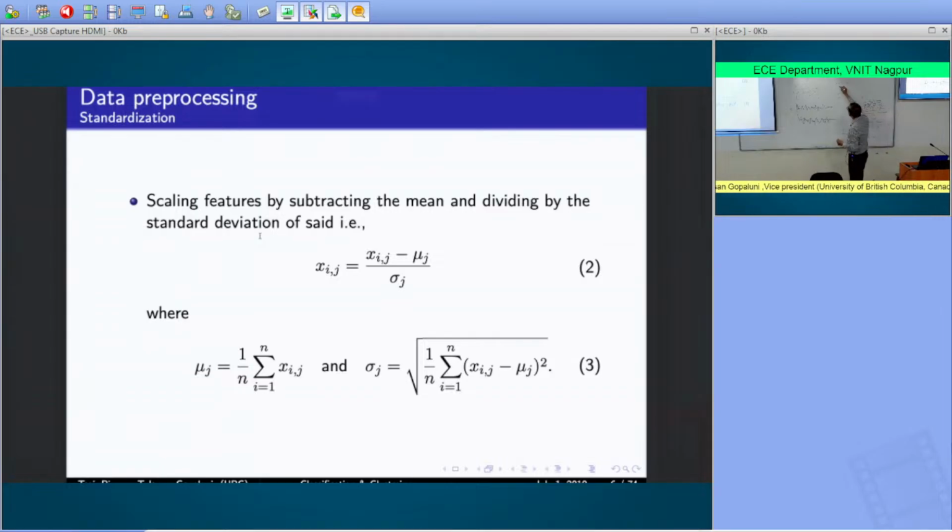Now, errors in temperature are going to be much larger than errors in concentration. If you have a typical optimizer and you don't weigh these two properly, your optimizer will focus entirely on the temperature errors, minimize those, and ignore the concentration errors completely. So you'll end up with a model that's good for your temperatures but not for your concentration. You want to make sure that the magnitude of different variables does not impact the optimizer or the performance of the model. That's why we want to standardize data.